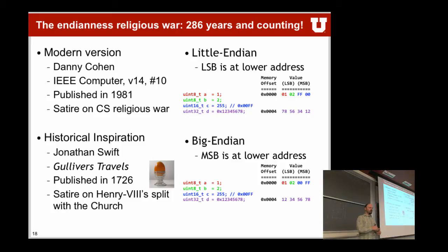ARM Cortex-M3s are by default little endian, but on many ARM systems you can switch at startup to big endian, so you can flip them around. There are also a couple of instructions in ARM assembly, more specifically REV and REV16, which will change a little endian to a big endian number. This is sometimes very useful if you communicate over a network and have to talk to somebody that's not little endian like you, so you can use the REV function to flip it around.